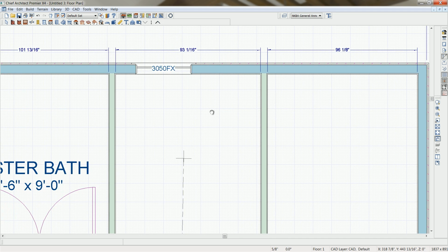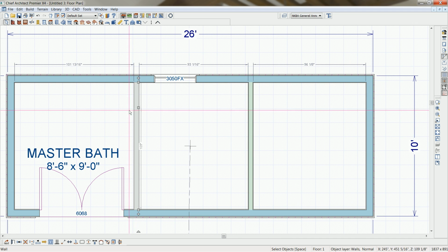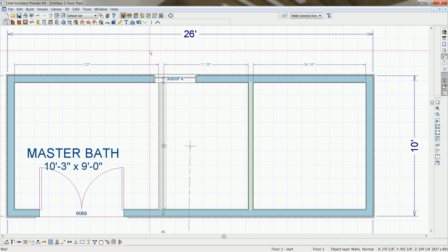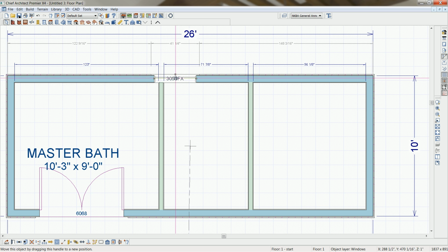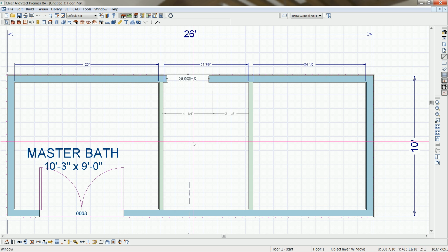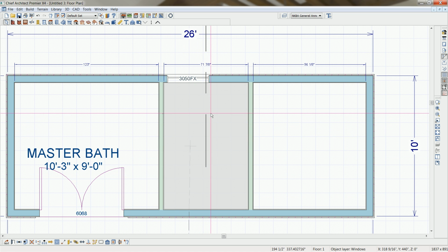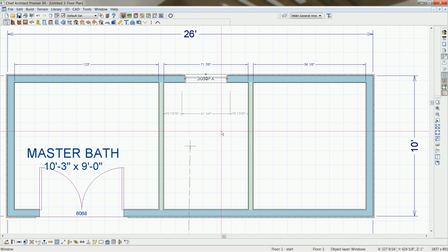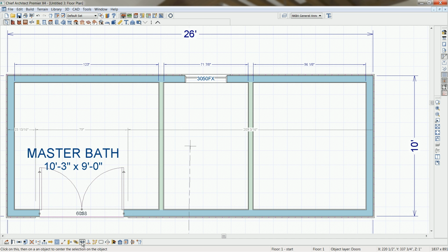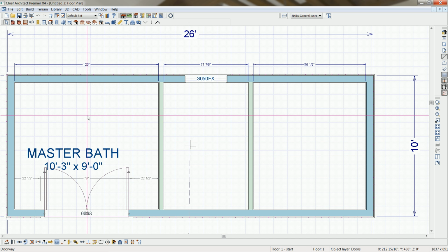So let's go ahead and lay out our walls. First wall, I want to have the interior dimension to be 123 inches. So I'm just going to select that. Let's go ahead and slide our window over. Now one of the tools that you'll find to make things easy is a center tool. So I've got that window selected. I'm going to select in that area of the room and press center, and that will exactly center that window. Let's do the same thing for our door over here. Center tool in the center of this room.